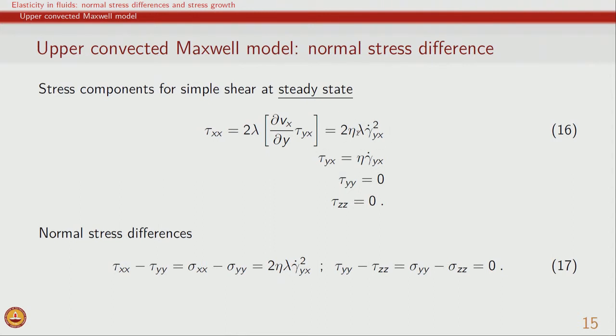Like we saw in the earlier case, where the Maxwell model by itself was able to give us a good response in terms of an exponential decay for stress relaxation. In case of oscillatory shear, it was able to show a transition from terminal viscous response to a glassy elastic response. However, when it comes to realistic materials, there are several other features which are observed, and therefore, the Maxwell model is not really adequate, though it does capture some elemental ideas of viscoelasticity.